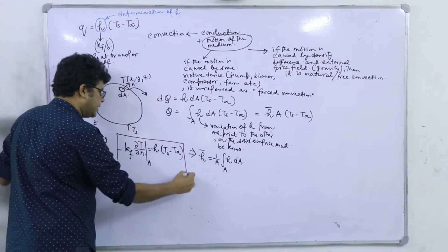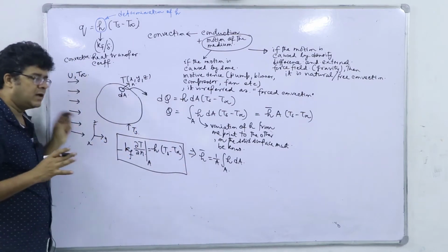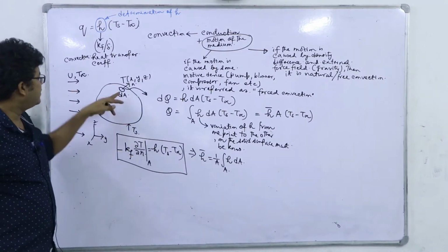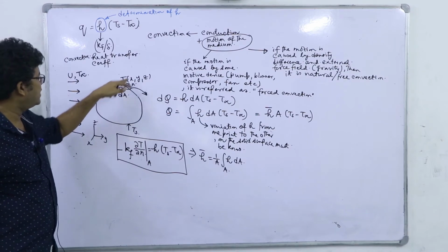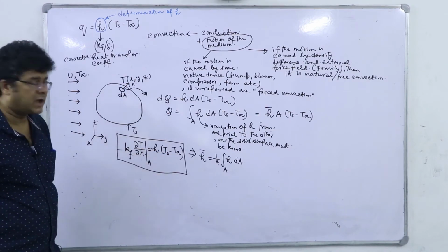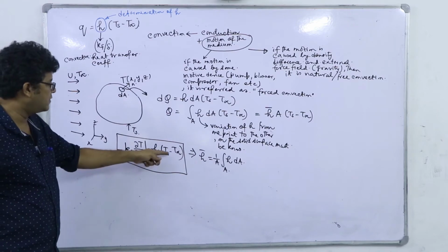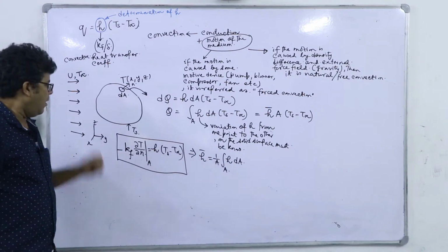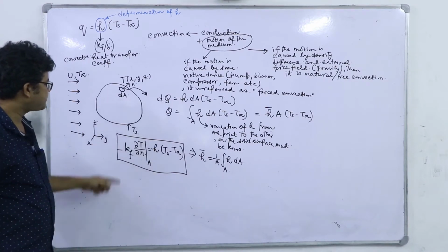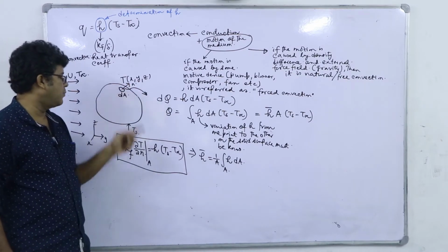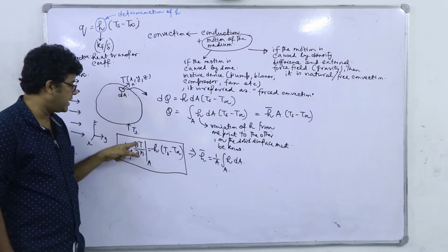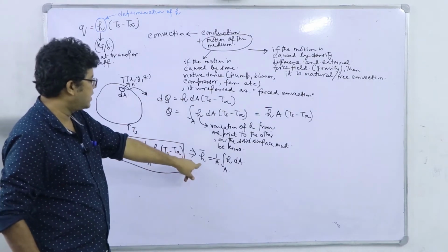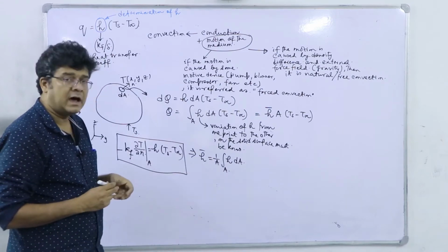So, this is a very important equation, though not in a working form; it is more a qualitative equation. N represents the normal direction. At this point the conductive transport must be equal to the convective transport. Ts is the solid surface temperature, which we are assuming to be uniform. T infinity is the bulk liquid temperature. So, if I can solve this temperature field, I definitely can find out this gradient, and from there I can get the value of h, which is to be integrated over this area in order to get this average h value.